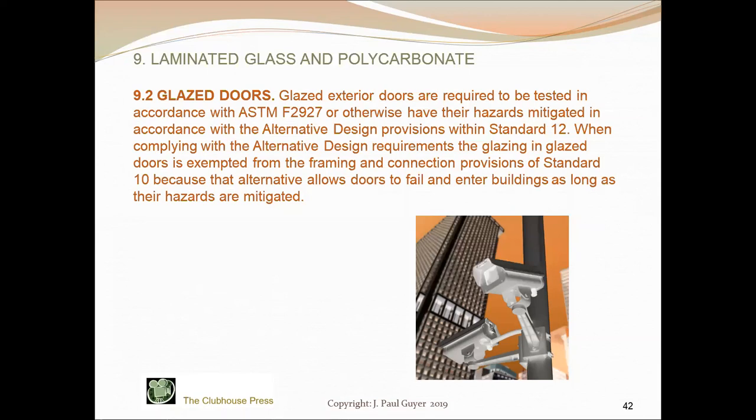Because that is allowed for exterior doors in general, to make the glazing meet all Standard 10 provisions would result in glazed doors effectively being held to a higher performance standard than non-glazed doors. Enforcing the glazing and frame height provisions of Standard 10, it's likely that the glazing will respond with the remainder of the door panel and that its hazard can be mitigated as an assembly as for non-glazed doors.